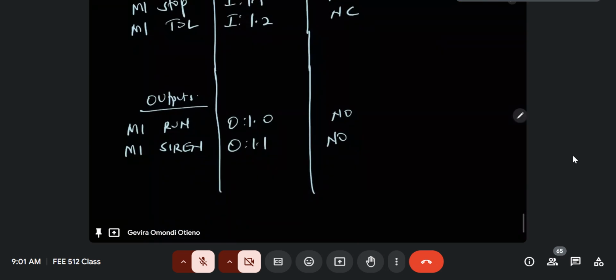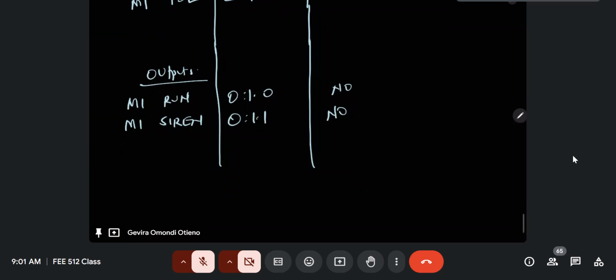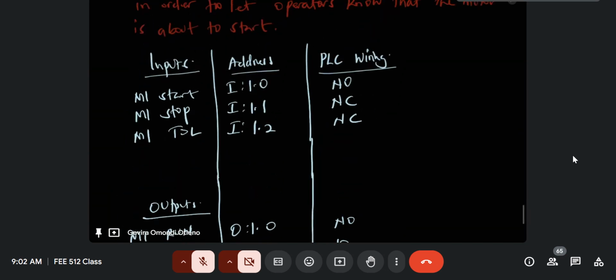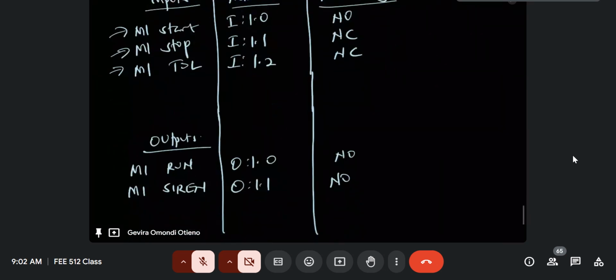So remember, we have some extra. I'm calling it extra because it's not a physical device. Extra start command. Remember, ladies and gentlemen, it is not a push button. When the siren goes off, I don't have to go and press the start push button. It's a start command. You see here, somebody has to physically press the button. Here, somebody has to physically press the stop button. Even here, there is a thermal overload that must happen before the downstream equipment is activated.